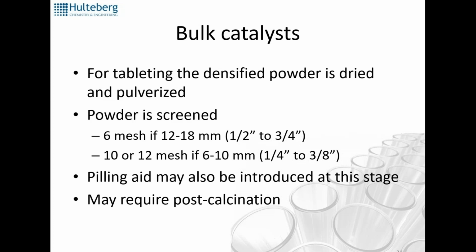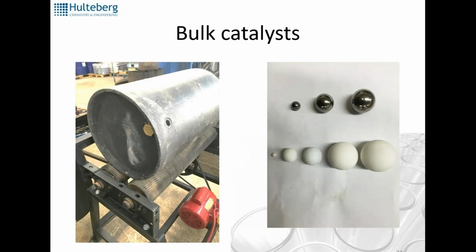And for the breaking up of the powder, we might have to do a grinding, and that can be done, for instance, in a ball mill. Ball mills can also be used for wet grinding, where you add water and a powder, most likely with alpha alumina balls, to make sure that you get a smaller particle fraction and a well-dispersed material slurry.